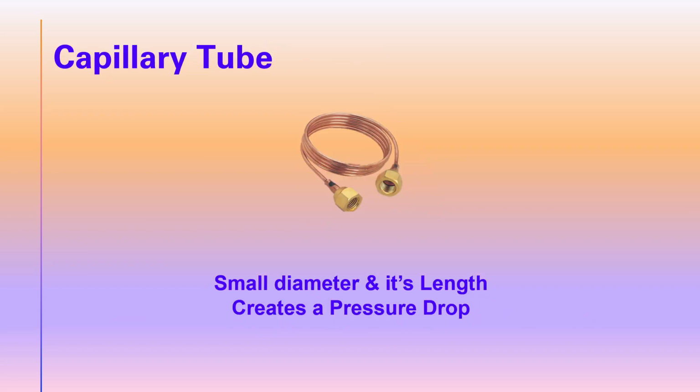Here's our first example, the capillary tube. This is used on mainly very small refrigeration systems, i.e. what you'd have in your fridge at home, and its small diameter of the tube and its length create the pressure drop. Now there are ways that you can calculate that, but we're not going to go into that here.